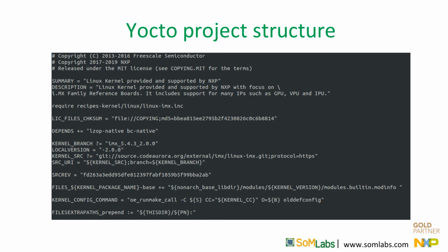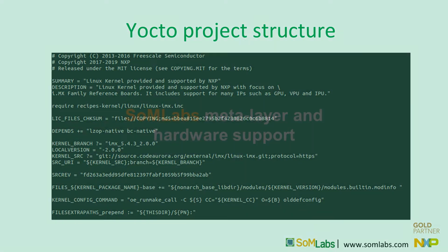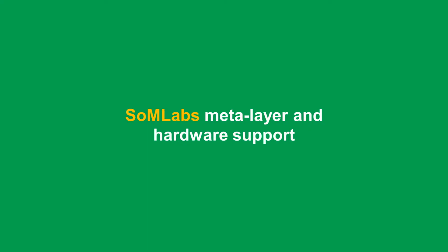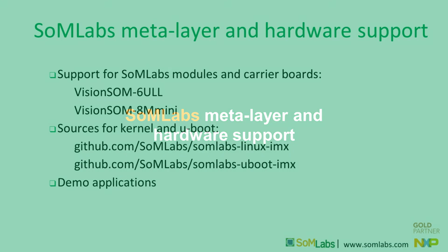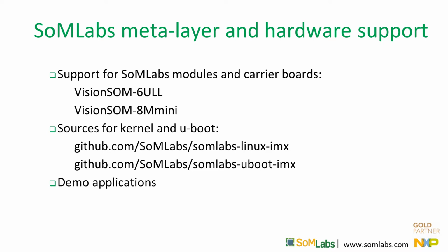Recipe files can also be inherited, as we will see in a moment when we will discuss the structure of the SOMLabs layer. The layer provided by SOMLabs allows us to build the Yocto NXP system for the VisionSOM modules. This support is currently available for both the older VisionSOM 6 ULL and the newer i.MX8M Mini with the corresponding carrier boards.